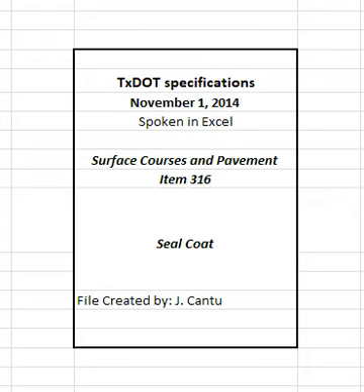4.14 Final acceptance. Maintain seal coat until the engineer accepts the work. Repair any surface failures. Before final project acceptance, remove all temporary stockpiles and restore the area to the original contour and grade. 5 Measurement. 5.1 Asphalt material. Unless otherwise shown on the plans, asphalt material will be measured by one of the following methods.